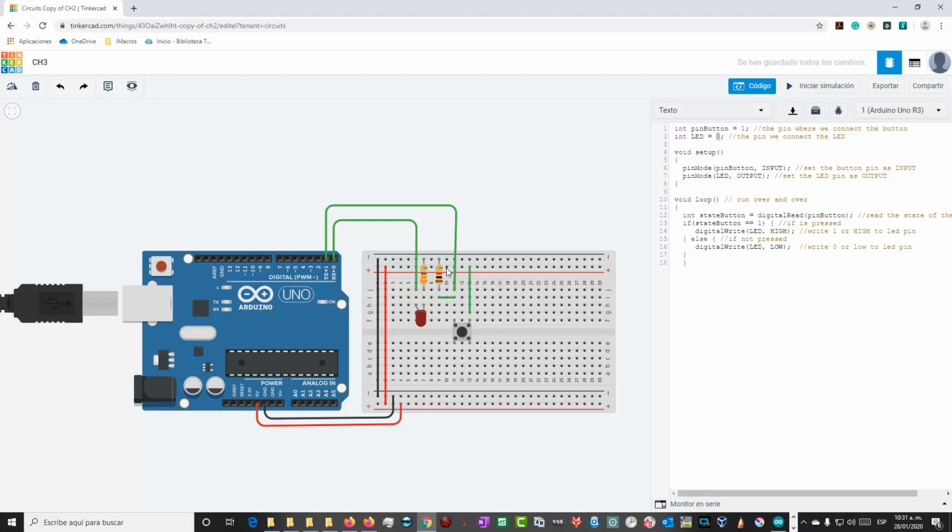This is really important for you to remember, and you need to be sure when you are using digital inputs and you don't have a proper digital value, you need to be sure that there is a 0. So connect this input to ground using a relatively high resistance, so when you don't push this button, this 0 signal goes to the card, and so the card works properly. So now let's see how this works.